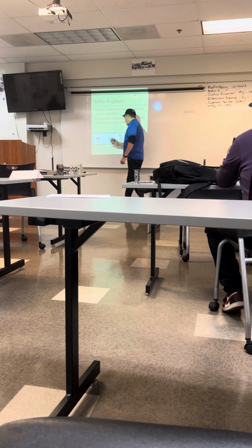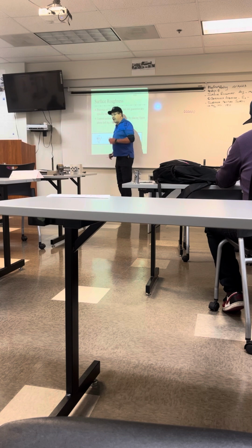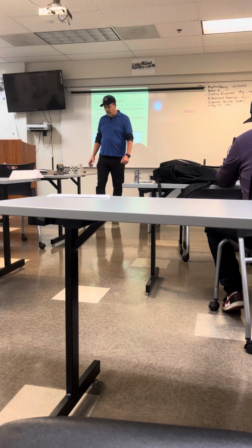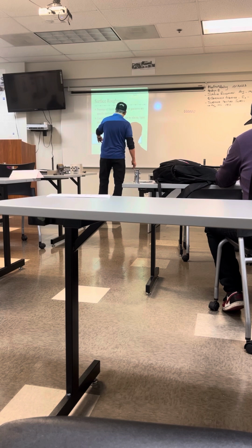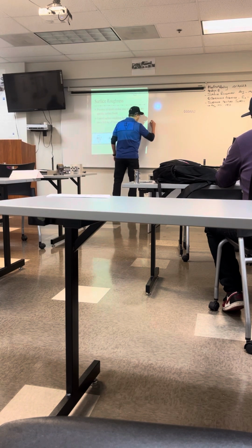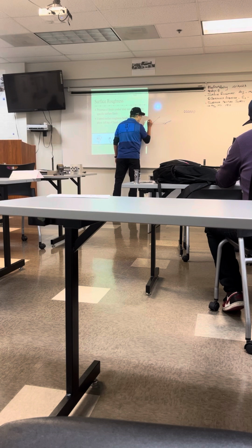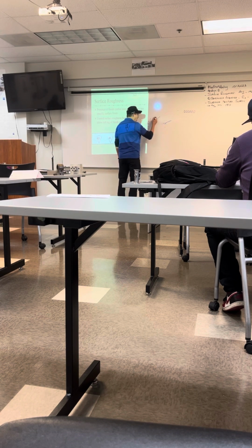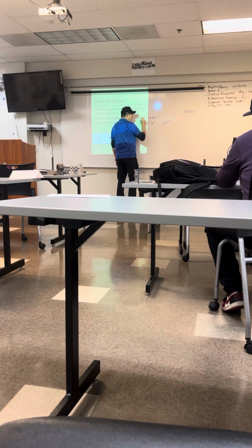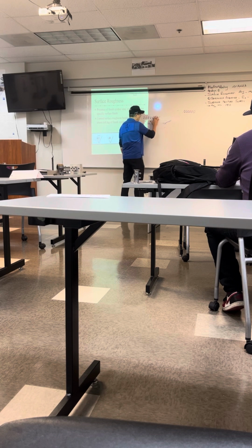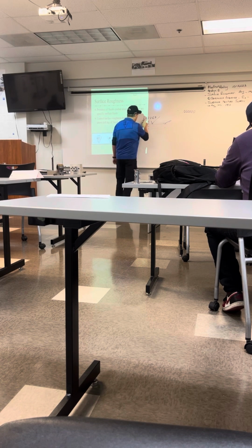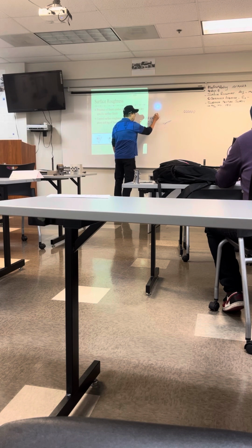Here, you see this number right there. That number is 63. But you also see that symbol right here. This is the symbol that they put on top of the surface to specify the amount of roughness that surface has. And they tell you 63 what? 0.000063. Let me see, 1, 2, 3, 4, 5, and 6 decimal places from the point.